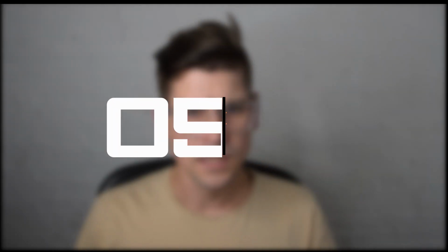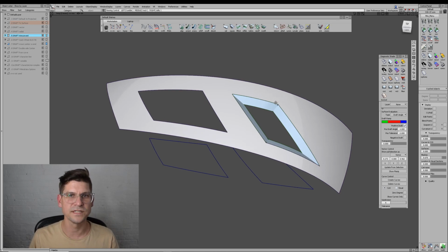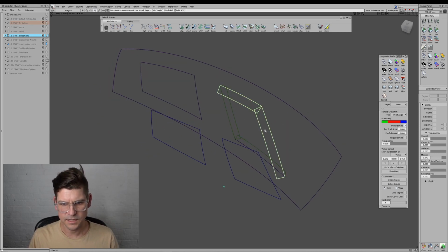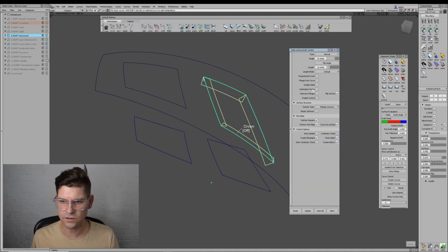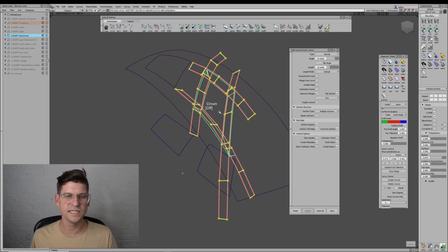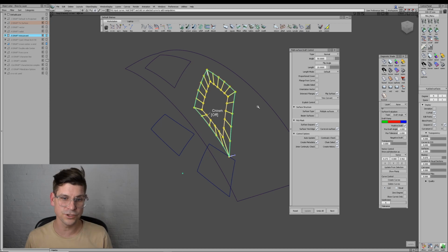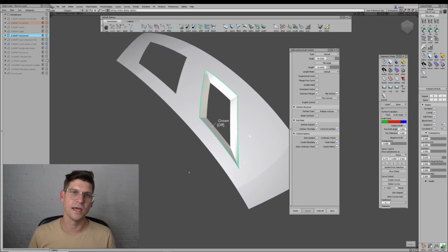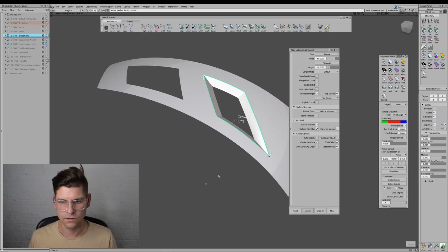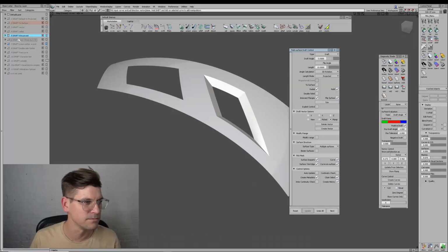Number 5 is how it trims the drafts in the flanges. So if we look here, these drafts are just intersecting. They're not trimming at all. So if I simply select those, I can say intersect flanges. I'll hit trim. And if we turn on the CVs, basically it just extended the draft and then trimmed those to intersect cleanly. If I switch this to trim convert, it actually does a trim conversion on that, making it a natural boundary in the corners. And now it's very easy to manipulate and to take it into Class A modeling. So intersect flanges, awesome little tool.